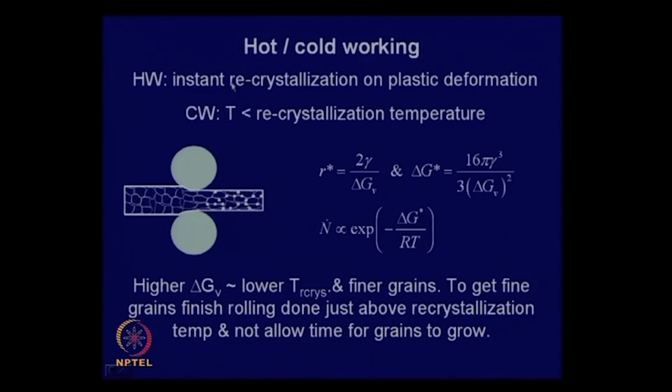We will talk a little bit about the recrystallization temperature. It is not a definite fixed temperature. It depends on a number of factors. It depends on the amount of working that you put in, the amount of stored energy that goes in during plastic deformation.